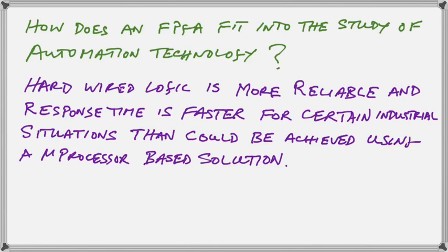Fail-safe systems and timing systems would typically want a hardwired system rather than an adapted or configured microprocessor-based system to achieve these objectives. So we can well use FPGAs in the overall SCADA system for those nodes where they are required, and where their additional speed will be an advantage.